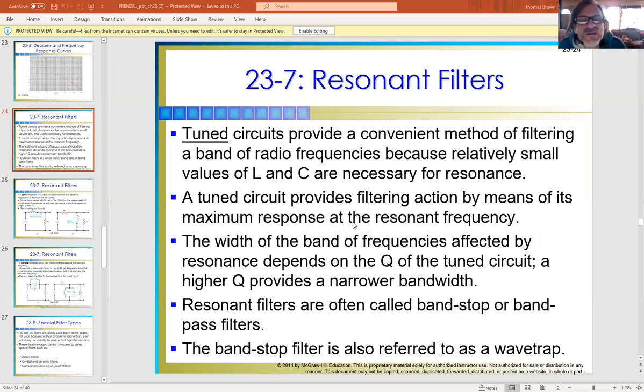And that's why they would call it a tuned circuit, because, as you've seen from the labs, our bandwidth region overall in resonance can be decently sized, but we really don't have a whole lot of room, right? So a tuned circuit goes along those lines where you would want just a specific frequency.